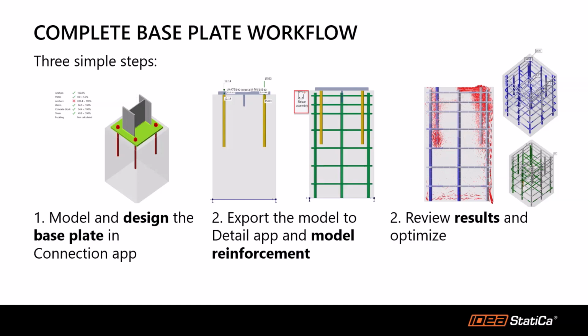However, EORs also need to design the concrete pedestal, piers, or even the foundation. So the integration is not limited only to when the anchors are failing for concrete breakout. The EOR can take advantage of the integration and design accurately the concrete below the base plate.